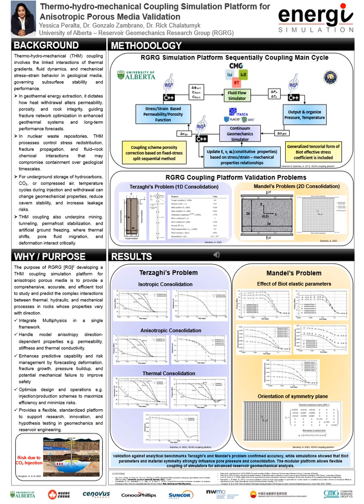In this case, we studied how directional differences in material properties affect consolidation. This is known as transverse isotropy, a condition where the rock behaves the same in one plane, such as the horizontal bearing plane, but differently in the vertical direction.